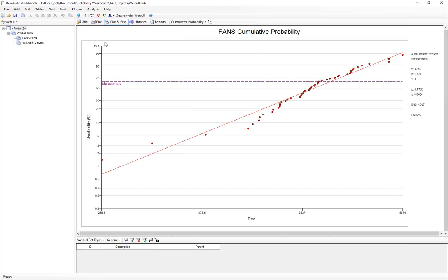What we usually use is something like a work order history, or something where we've recorded failures for a component. In this example, I have two cases: a fan motor and a set of valves. I recorded those valves, a whole bunch of them operating over time. Every single time one failed, I recorded how many operating hours I got out of that component before it failed.